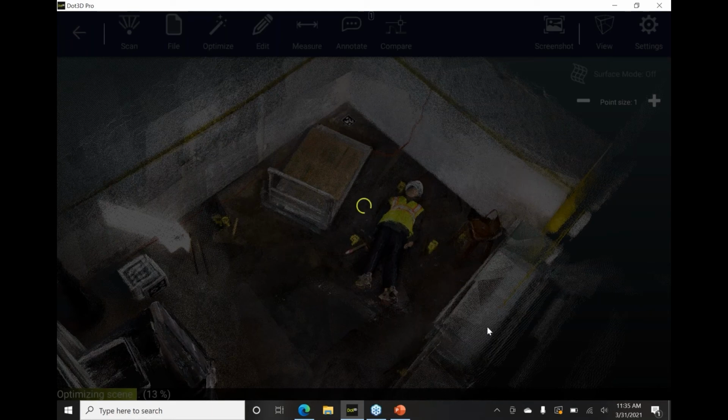Essentially, anytime you hit the same unique tag more than once, the software automatically recognizes I've been to the exact center point of target number 7 at the beginning and the end of my scan. If in the unoptimized data that target wasn't quite perfectly lined up, maybe it was a little bit off, at least in the unoptimized scan, that April tag recognition will guarantee that those are going to be exactly aligned. And if you can understand that, you realize that'll make every single point in your cloud a little bit more accurate, totally automatically and totally behind the scenes.